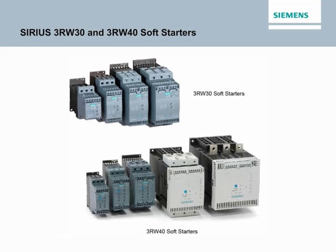Sirius 3RW40 soft starters have all the advantages of 3RW30 soft starters, but have more features and are available for operating current up to 432 amps at 40 degrees Celsius. 3RW40 soft starter features include selectable motor overload protection, class 10, 15, and 20, manual or remote reset, and optional thermistor and motor protection. 3RW40 soft starters are also equipped with integrated intrinsic device protection to prevent thermal overloading of the power switching devices, the thyristors. Potentiometers on the front of the unit provide settings for the current limit, starting voltage, and ramp up and ramp down times.